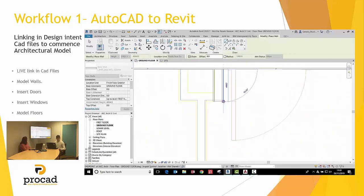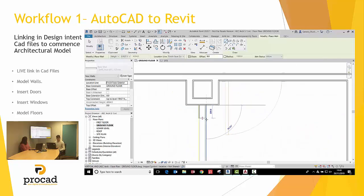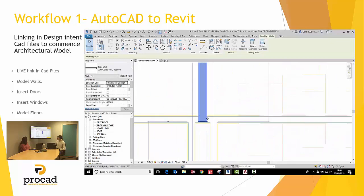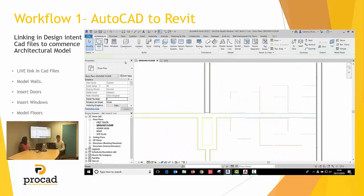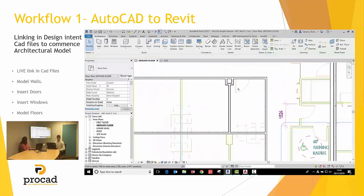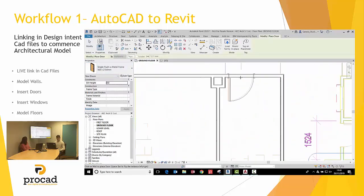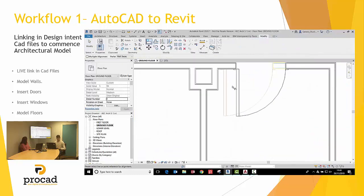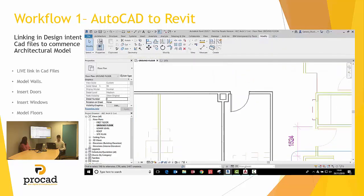I'm going to again carry on using internal walls, and you can see here that I'm going to make a mistake. That wall is actually supposed to end at this point, and it's simply left clicking on the wall, clicking on the blue bubble, and dragging it back to the location that you want. Next, I'm going to do doors, and the reason that you always start with walls is that the doors can automatically be inserted into the walls.